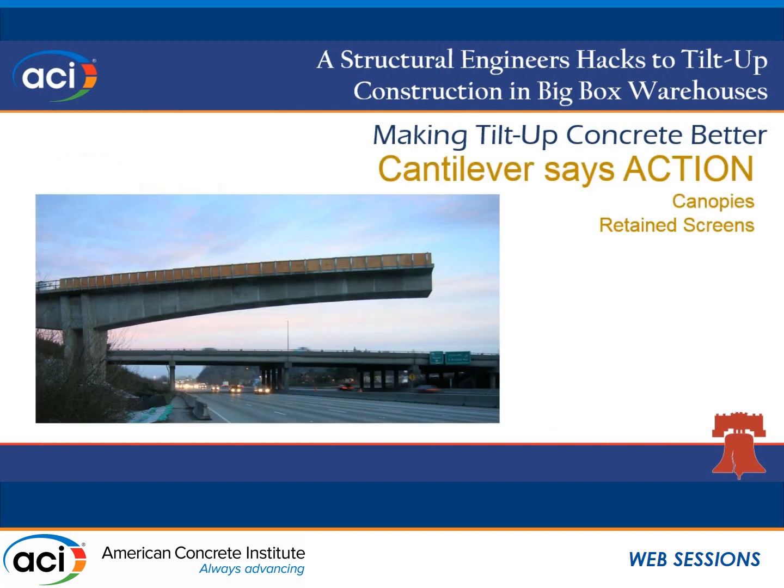Last one, cantilevering panels, okay? So screen walls, retaining walls, you can do it. When you have a cantilever panel, there's a detail I'll show you later, but the idea is basically you build it in the tilt-up world with the panel first, then you pour the footing around it. You want to account for all the behaviors of the panel. Slender wall analysis doesn't really work. Your conventional concrete analysis here.